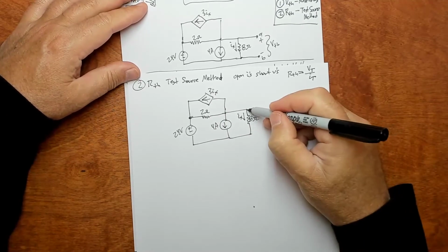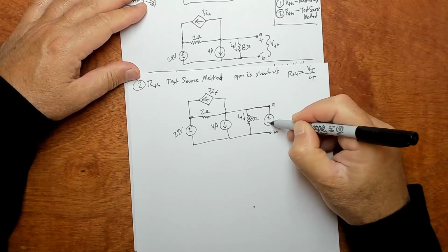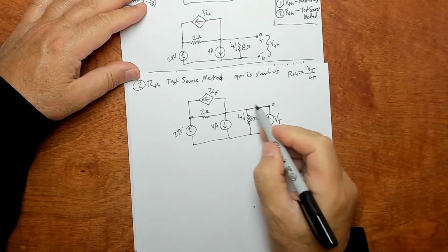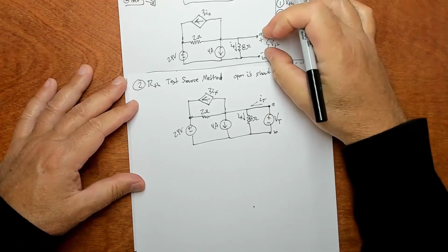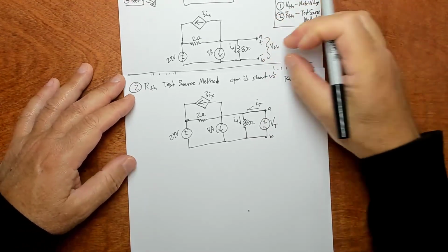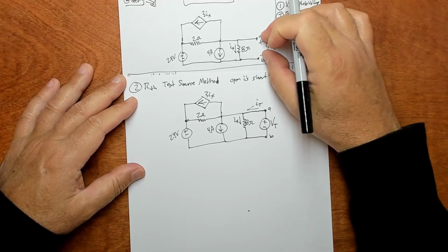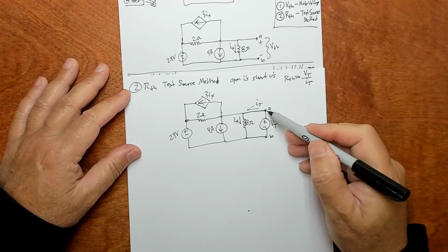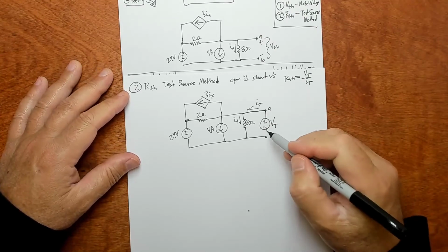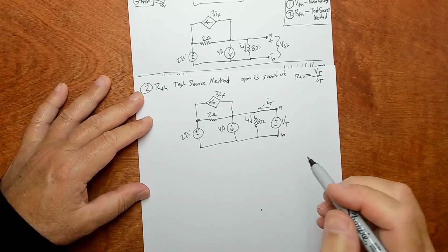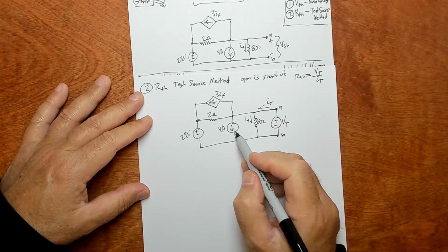Okay, there's our original circuit, and what we're doing here is across terminals A and B, we're inserting a test voltage, V sub test. And that test voltage is going to have a current associated with it called I sub test, right? Okay, so we started out with an open circuit across AB, at least in terms of the Thevenin equivalent. We're looking at this as an open circuit. And now we're kind of closing that up by attaching a test device. Now if we do that, then what happens is, oh, I forgot to open the I's and short the V's, didn't I? Yes, I sure did.